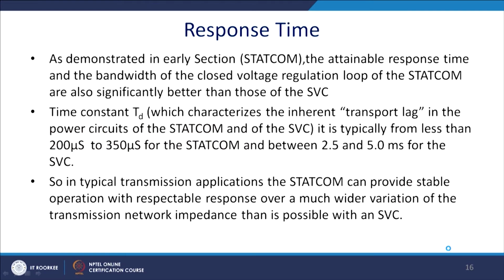As demonstrated earlier, the attainable response time or bandwidth of the closed voltage regulation loop of the STATCOM is also significantly better than the SVC, because we have discussed that the SVC has to wait for the cycles to start and all those things, but in the STATCOM you can change the modulation index very fast.